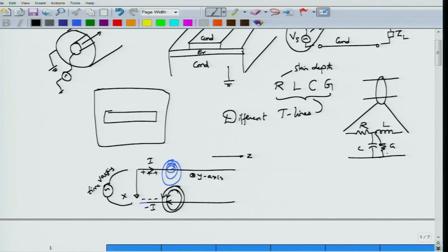So the charge distribution also varies over the transmission line conductors, and the moment there are two charges of opposite polarity, there would be an electric field. So you have electric fields down from one conducting wire to the other, so let's call that Ex, and then you have the magnetic field. I am not going to write down the vector notation because it is not really important here. The magnetic field lines are mostly confined in the plane transverse to both x and z directions. The magnetic field lines are in the direction of Hy.